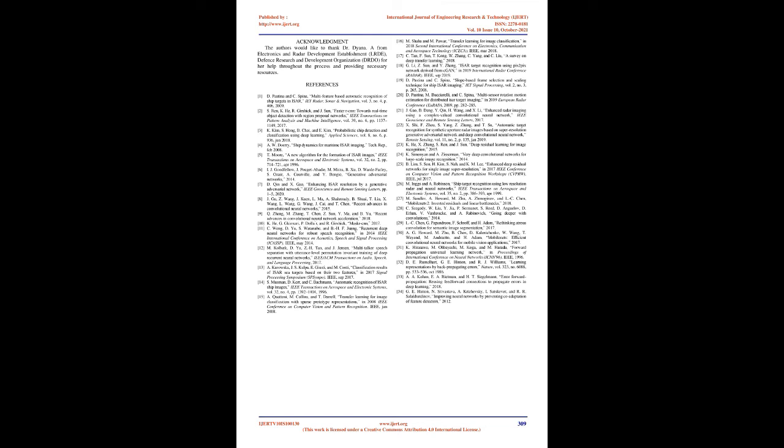As for the ISAR image classification, the transfer learning technique is utilized to achieve a state-of-the-art solution. The model used is MobileNet v2, which results in an accuracy of 100% on the training dataset and 90% accuracy on the validation dataset. The results shown here are compared to existing methods such as multi-feature ATR, where the author obtained an accuracy of 89.7% and 91.6% for single frame and 2 frame, respectively, with known aspect angle. The proposed method outperforms in terms of real-time prediction and pre-processing towards the algorithm.